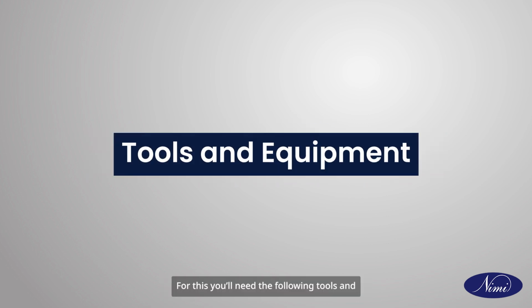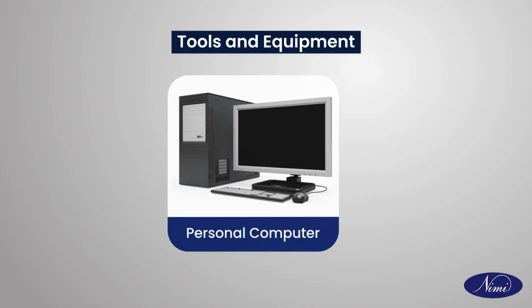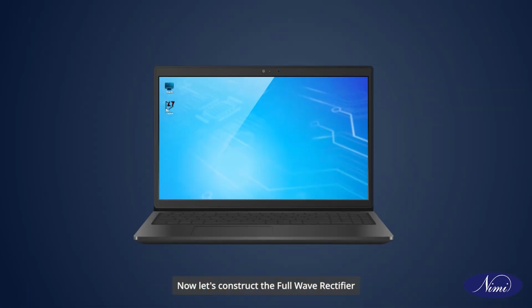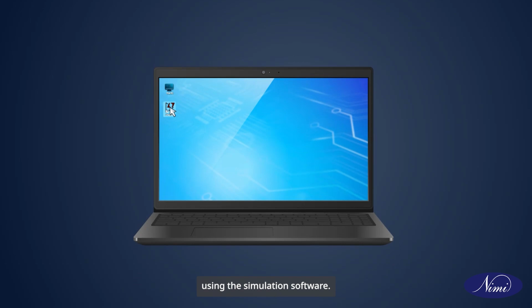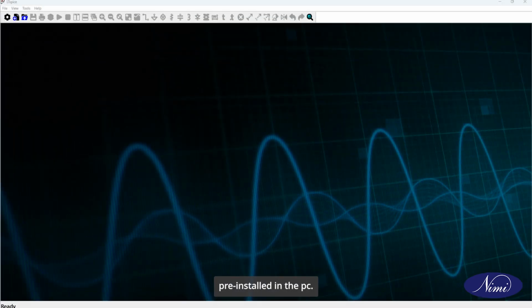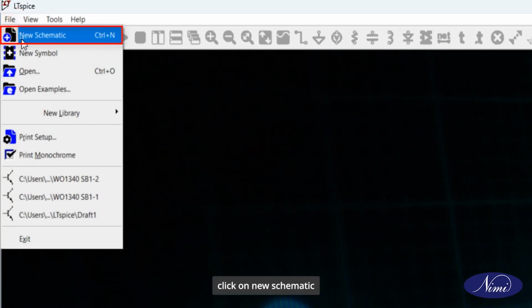For this, you will need the following tools and equipment such as a personal computer and simulation software installed in the personal computer. Now let's construct the full wave rectifier using simulation software. First, open the simulation software that is pre-installed in the PC. To create a new file, click on New Schematic.